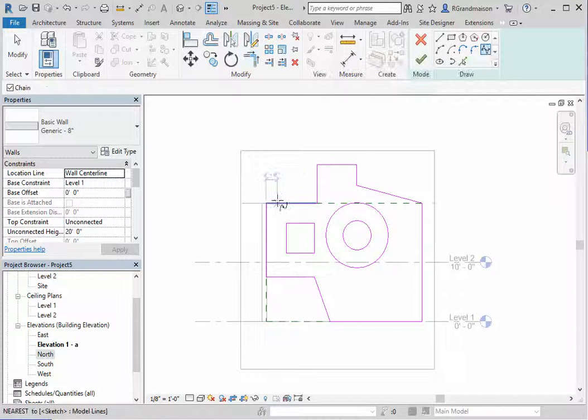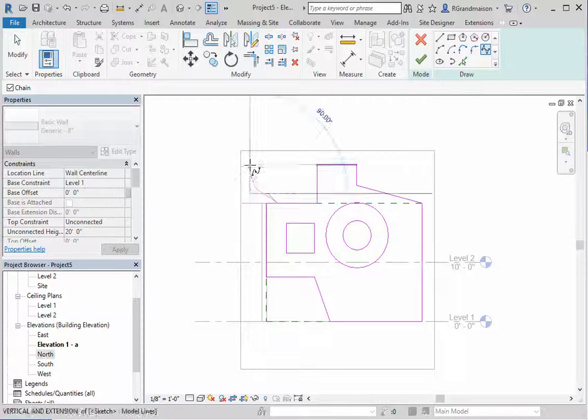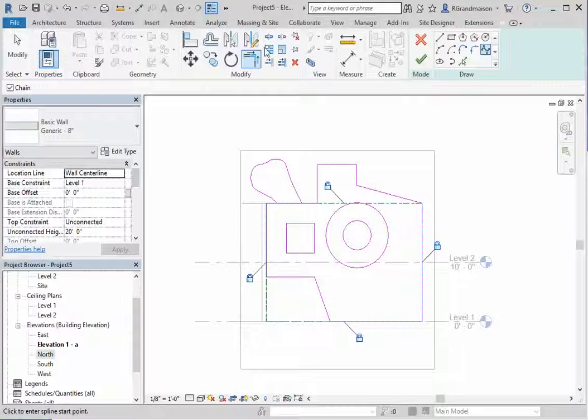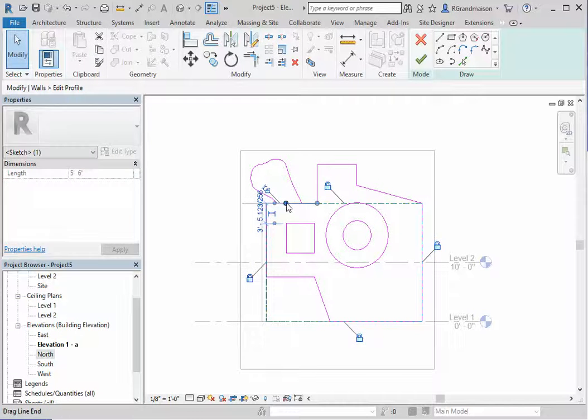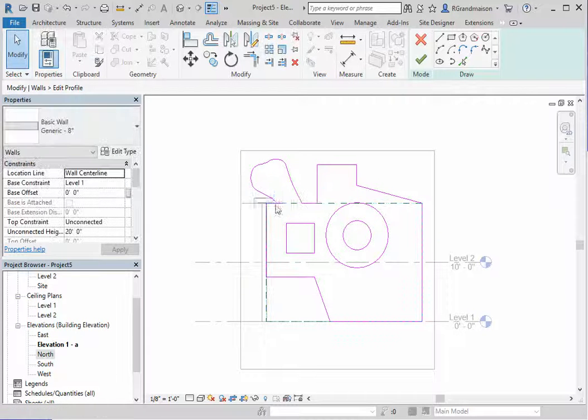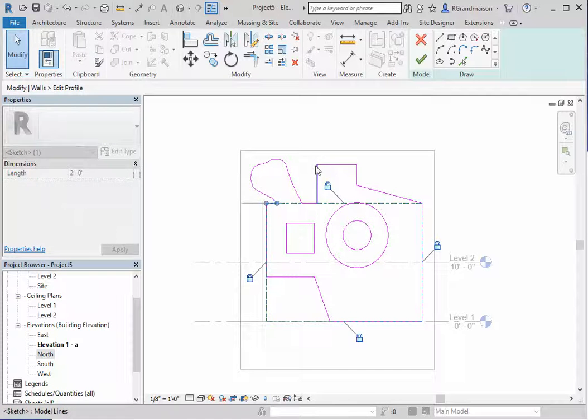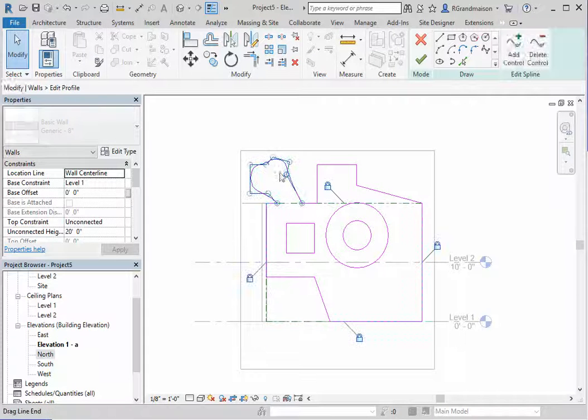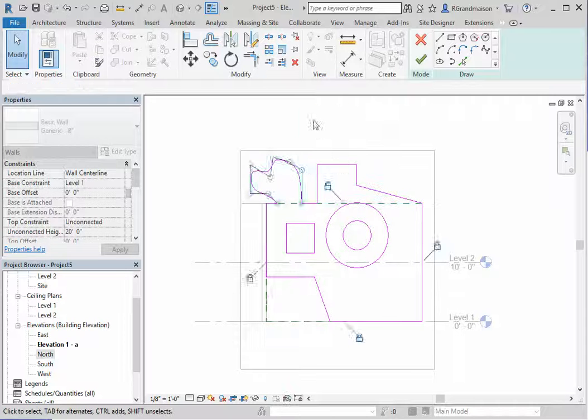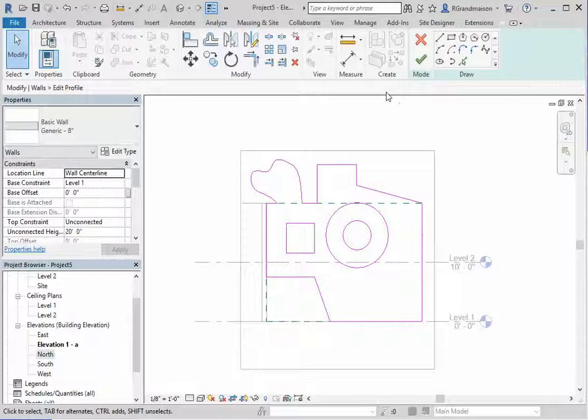And there are other tools too. You could use a spline tool here. Let's do something wild and crazy out here to see what happens. We'll just put some strange object up here like this. I'll come back to here, and I will go ahead and use the split tool to break this into two parts. You can't use the trim tool when it comes to using splines like this, so you have to instead just use your O-snaps to change the location on that one over to the endpoints on the spline. You can always edit the spline afterwards if you want to change the shape of something here. So there we have some strange form coming out of the top of this thing here.